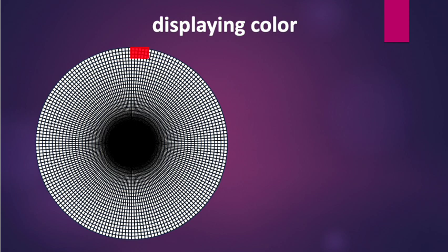However, this method can only be used in a modified form in the rotating display. This is because the time that a single pixel is displayed is very short. It is in the order of magnitude of 100 microseconds. However, a typical pulse width modulation would modulate the LEDs much slower.